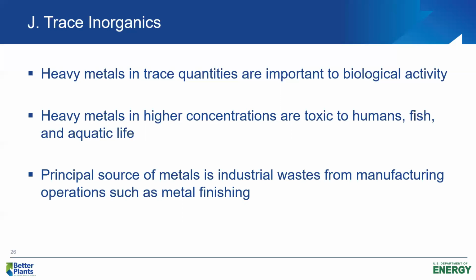But if they come into the treatment plant in concentrations that are too high, they can be toxic to our bacteria. They can pass through into the receiving stream and be toxic to fish and aquatic life. Heavy metals in high concentrations in drinking water can be toxic to human beings.